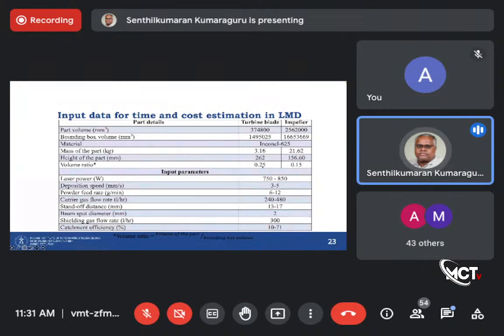The volume ratio is also defined, which is the volume of the part to the bounding box volume, which is going to tell us a lot about the buy-to-fly ratio, because your stock will be the bounding box. If your part volume is much less than the bounding box, then your buy-to-fly ratio is going to be very high. That means the impeller will have the poor buy-to-fly ratio, which is ideally a good case for near-net shape, stock-based near-net shape feature partitioning.